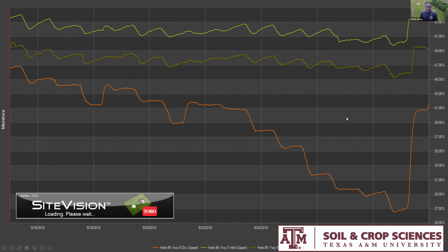This is just an example of, I don't know the date here, we probably did maybe a 10-day dry down to determine our thresholds of when to trigger the irrigation for these particular zones. So we went out, we mapped soil moisture, we created the irrigation management zones, we strategically placed these in-ground sensors, and then we conducted a dry down with the superintendent.